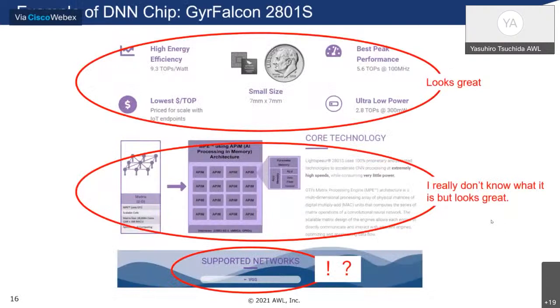As I mentioned, the deep neural compute chip is very powerful for constructing an edge AI camera. However, the deep neural network chip has a difficulty: the supported operators are very limited. So it is very difficult to port a model that works on an NVIDIA GPU machine.